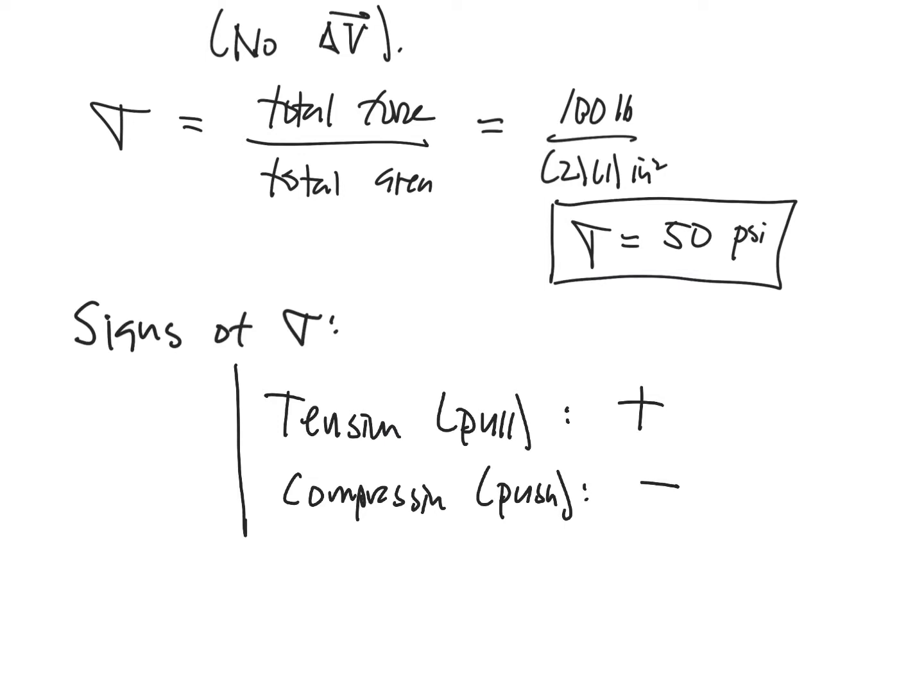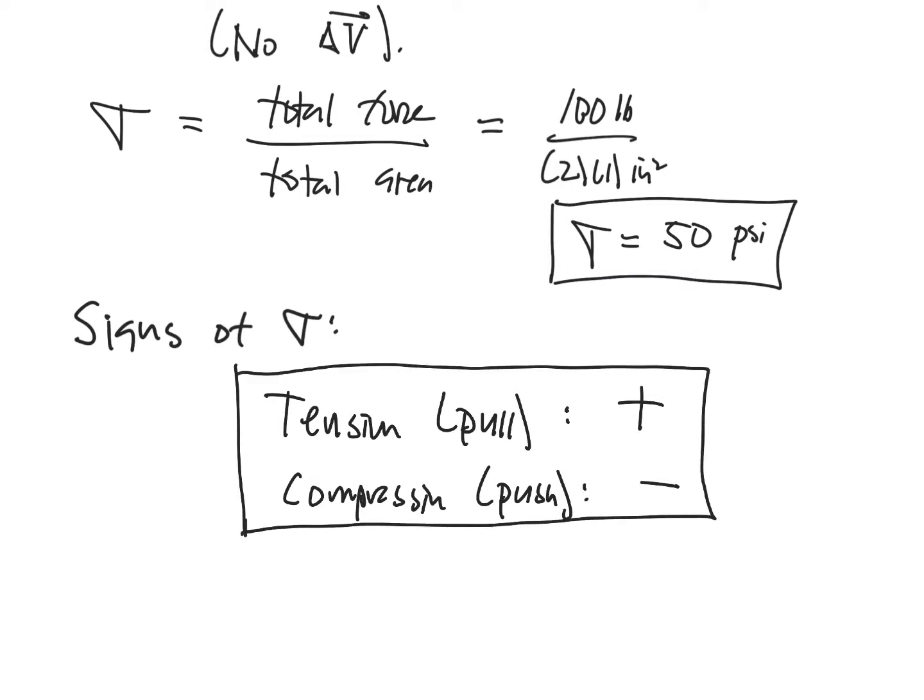So the sign convention for the stresses is very intuitive, kind of natural. If I pull something out, making it grow longer, it's considered a positive normal stress. If I'm pushing it, it would be negative. Up here we would denote the sign by using the letter T for tension. So we could say T or we could say positive; those would be synonymous.